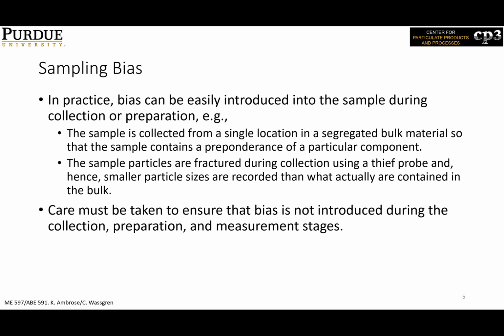In general, two types of sampling error can occur within a powder system with a mix of different particles or components. The first is heterogeneity caused by differences in chemical and physical properties of the particles themselves. The error caused by this heterogeneity will be difficult to control even if you have a foolproof sampling method. The second type of error could occur from distribution heterogeneity due to non-random distribution of particles within the powder bed. But this heterogeneity can be overcome by following a good sampling scheme or sampling procedure.